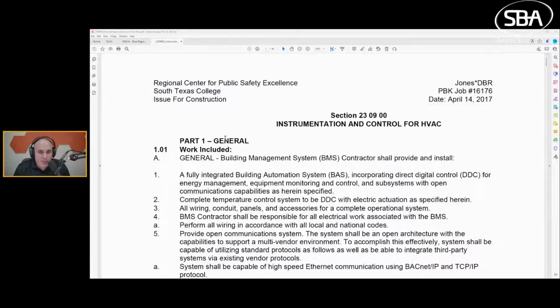So that's inputs. Outputs, we've got our standard digital outputs, DOs, sometimes called voltage outputs. This is typically 24 volts AC for things like on-off actuators, on-off relays, etc. It can be both internally and externally sourced. And we have our floating outputs. These are two outputs with a shared common, clockwise and counterclockwise rotation.